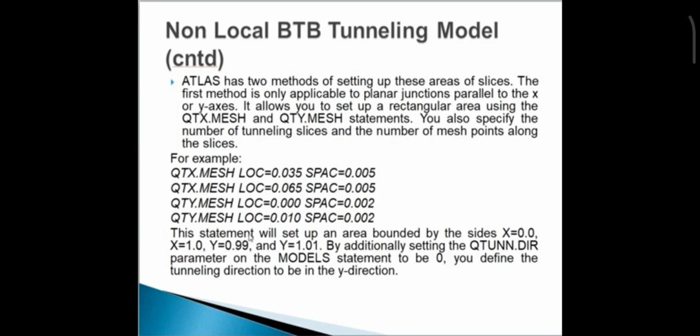This statement will set up an area bounded by the sides. By additionally setting the qtnn.dir parameter on the model statement to 0, you define the tunneling direction to be the y direction. If the tunneling direction is in the x direction, then set qtnn.dir to 1 on the model statement. It is recommended to have as fine a mesh as possible in the tunneling direction, both for the physical mesh and